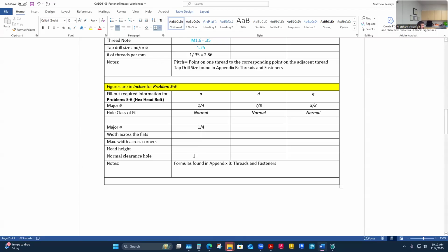It really is just the threads of a bolt, but it's got a different head shape for a countersink fit, or a counterbore is like a socket head machine screw. Really it doesn't mean their threads are any different. To say one's a screw and one's a bolt in this kind of world is saying the same about the threads. But where you might get confused is you might call a screw that really coarse thing for a wood application. We call that a screw, and it's made to cut its own way through materials. So don't confuse that kind of thread relationship with what we call a bolt, and we call it a screw as well.